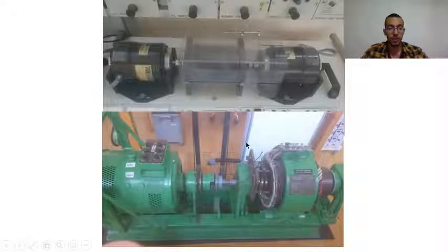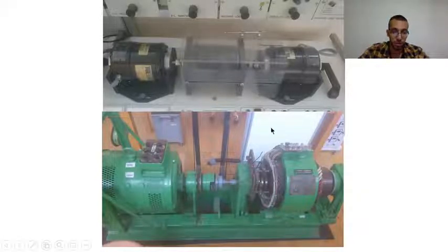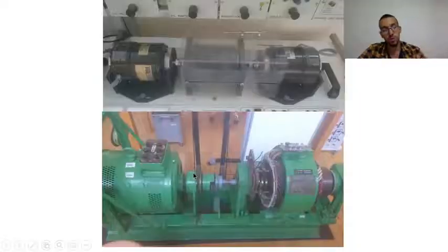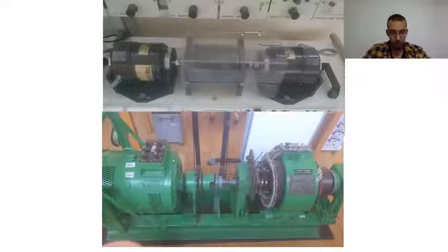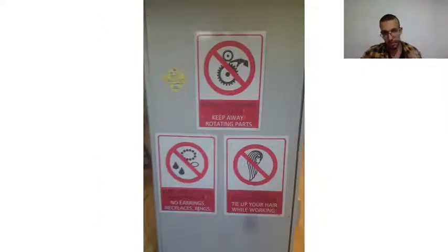They revolve at really high speed, and they have some open parts like you see here, and we don't want to get caught up in those, okay? We don't want to get close to them. Also, we don't want our necklace, earrings, rings, or any other loose parts, loose clothes, for example scarves that we wear in the winter, to get caught up in the rotating parts. So we take them off, leave them at the entrance, on the clothes hanger, something like that, and we keep away from the rotating parts all the time.